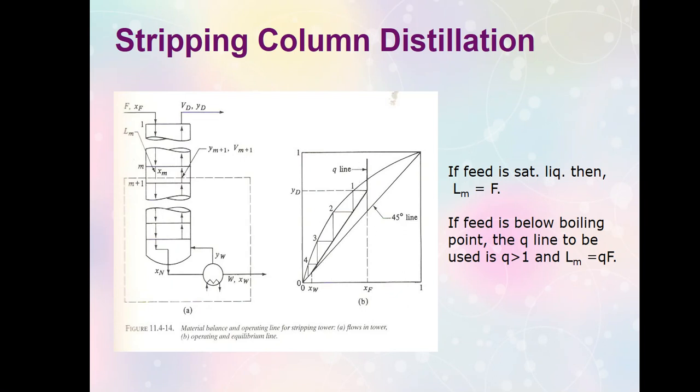And you're using here the YD, or the mole fraction of the vapor that goes up the column, carrying with it the volatile component, or the most volatile component. This YD anyhow is just the same as XD, because whatever is the mole fraction in the vapor here is the same mole fraction in the condensed liquid equivalent. So this is how you accomplish it using graphical approach.